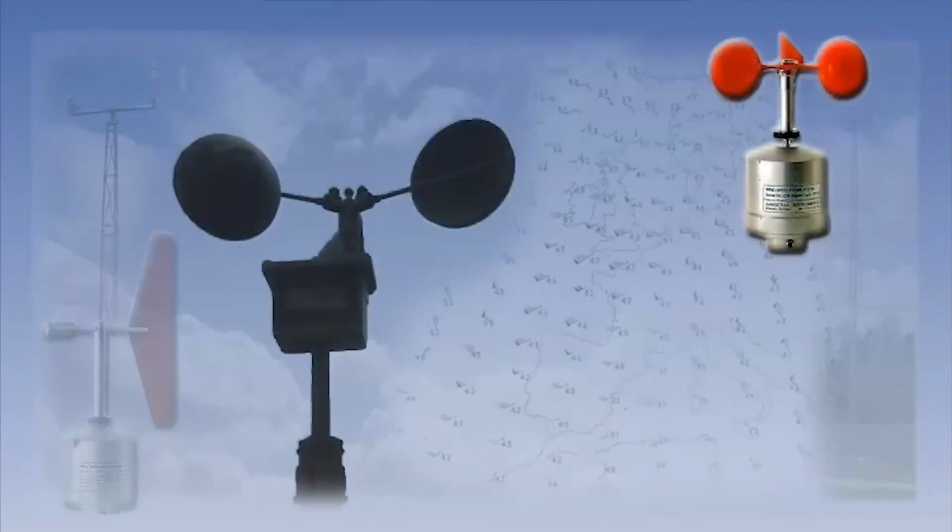Measuring wind velocity is quite simple. The most widely used instrument is the cup generator and wind vane, which is shown here. The three cups capture the wind, and as a result, they will rotate about a spindle. The rotation of the cups drives a sensitive electrical generator. The greater the wind's speed, the greater the voltage generated. The generator moves the pointer around a dial graduated in knots.